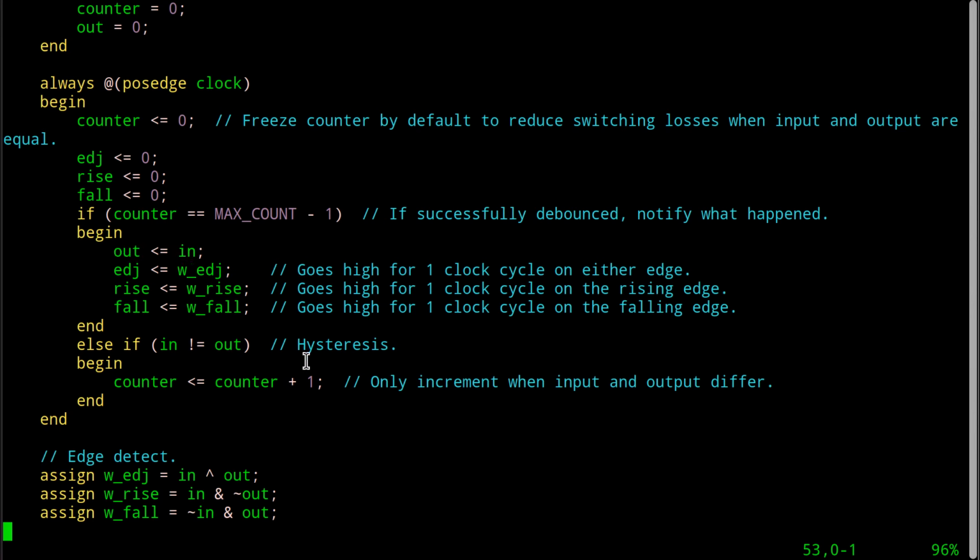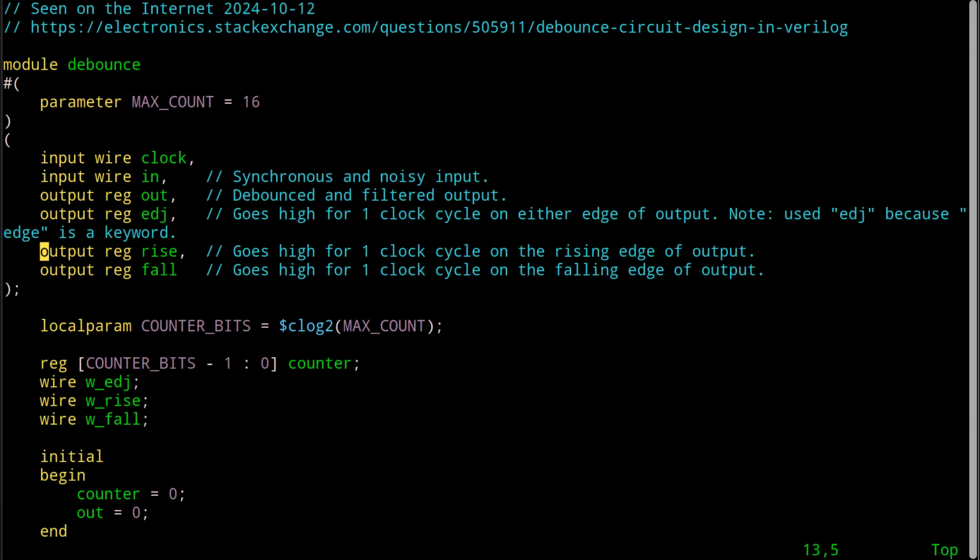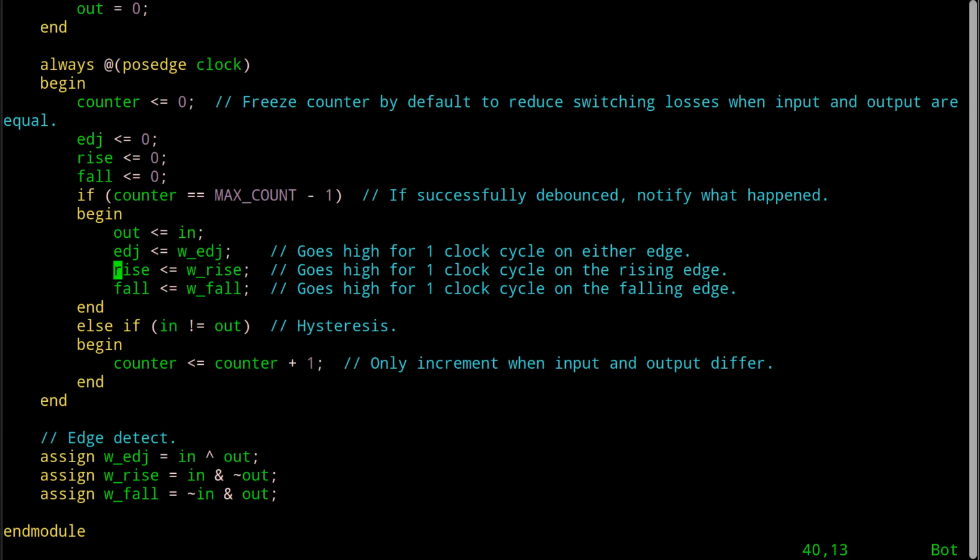Okay, so that is the other tidbit here. Make a nice general purpose library like this so that you have this if you need it. Don't waste your time optimizing. The compiler's not stupid. If you're not going to use this signal, it knows to go and throw away everything that ever generated it all the way back to whatever inputs are still in use for some other reason. And you save all those LUTs, okay?